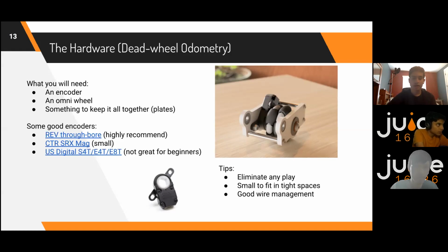Another thing that you could also implement is making sure that your odometry module is sitting on the actual surface, and you can use rubber bands or whatever to hold it there. You'll have inconsistencies in the floor mats or certain obstacles and things, so you always want your wheels to be tracking.